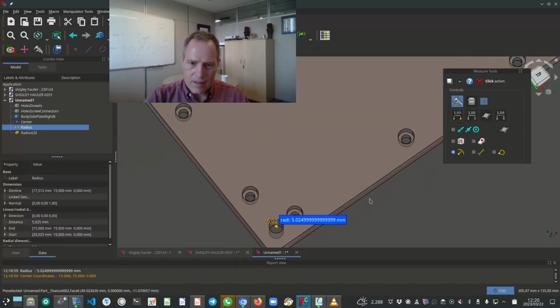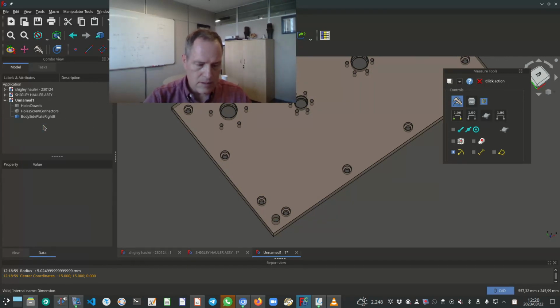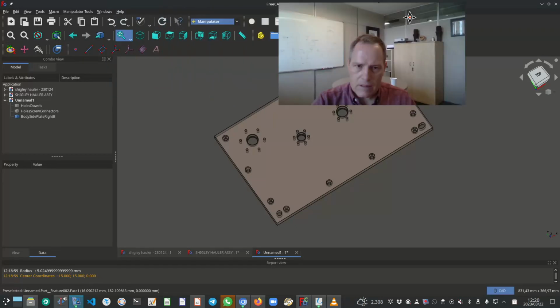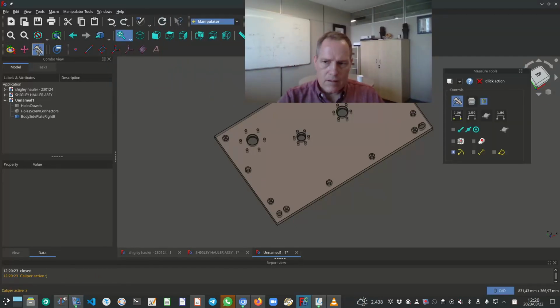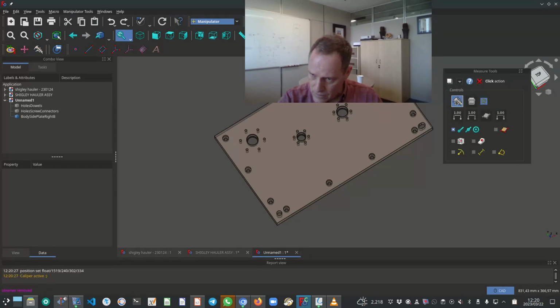With that said, once again, you can highlight your dimensions and delete them. Now what I also want to tell you here, if something goes wrong with the caliper, you can close it and open it again. Make sure you click the caliper, it must be highlighted. The default setting is a probe. We want to measure diameter or radius, so the caliper needs to be highlighted, and this yellow arc needs to be selected.